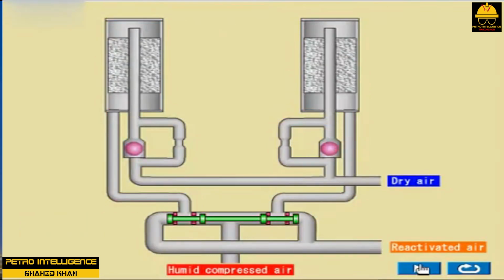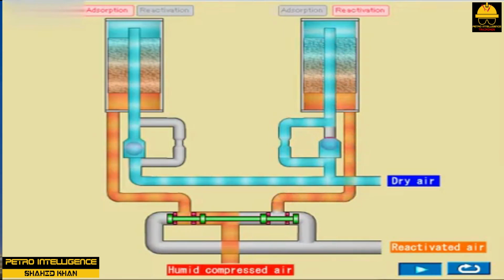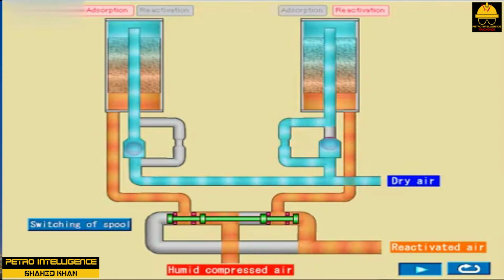The regeneration of the solids in a gas dryer can be considered a small-scale operation of drying the granular product from a chemical plant. In the case of a final product, the quantities are usually so large that special equipment is used to handle it, but the principle is the same. The moisture adhering to the solid is vaporized and carried away by a gas stream because the vapor pressure of the moisture on the solid is lower than that in the gas stream.